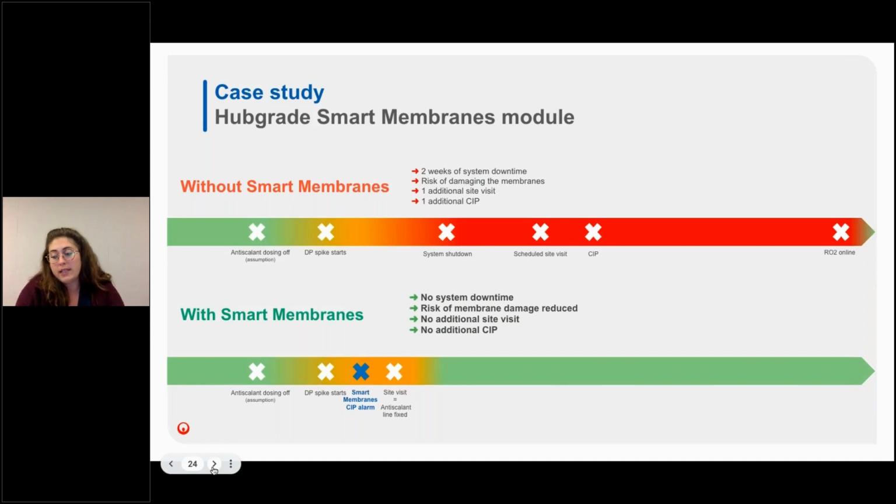We don't know the exact date when this happened, but by looking retroactively at the data analysis provided by Smart Membrane, it is clear that it could have been easy and quick to detect that the unit was becoming heavily scaled, in particular on its second stage, just by looking at the normalized data trend and receiving the predictive maintenance alerts. Since no such monitoring was in place, the unit continued to scale until an automatic shutdown on high differential pressure alarm on the 14th of June.